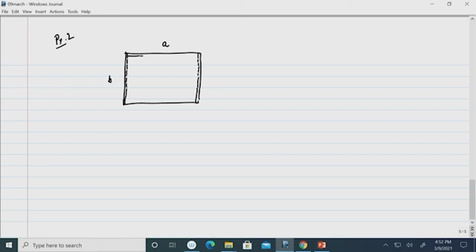In addition, for the boundary conditions on the other two edges, the edge at y equal to 0 is again simply supported, and here we have taken a fixed edge. So, you can see this is simply supported, this is simply supported, this is simply supported, and this is clamped. Because of the purely unsymmetrical nature, we cannot take any advantage of symmetry, that means omitting two constants and retaining two constants, that cannot be done here.